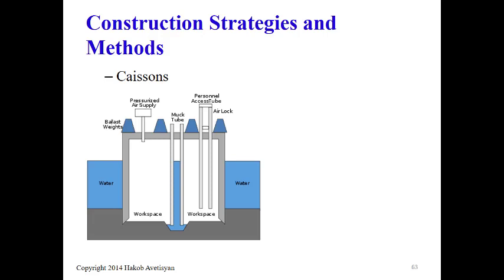In that workspace, if it's large, then construction equipment can operate. If it's small, then people can operate directly on that floor and excavate, and under its own weight, it will continue penetrating deeper and deeper into the media. Well, this is a pressurized system, and it's an unsafe condition for any human being to work in continuously.